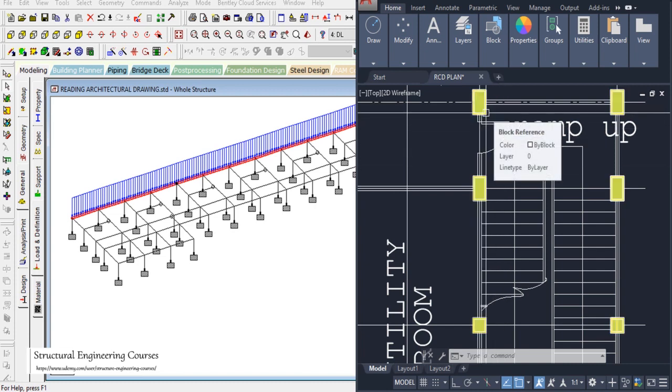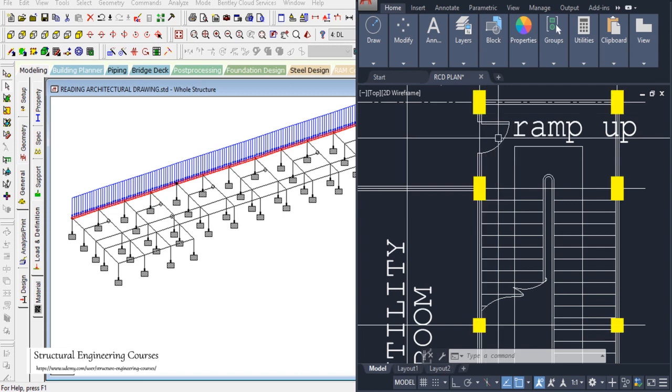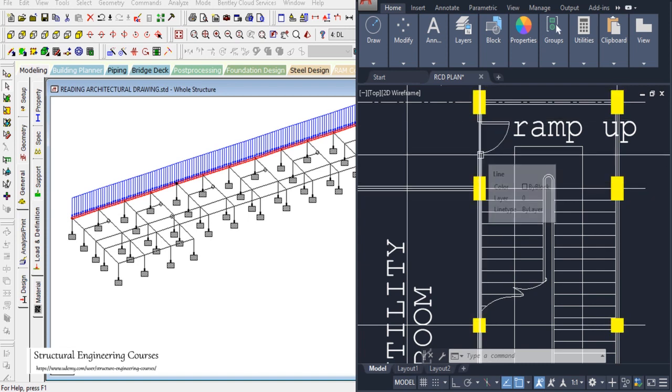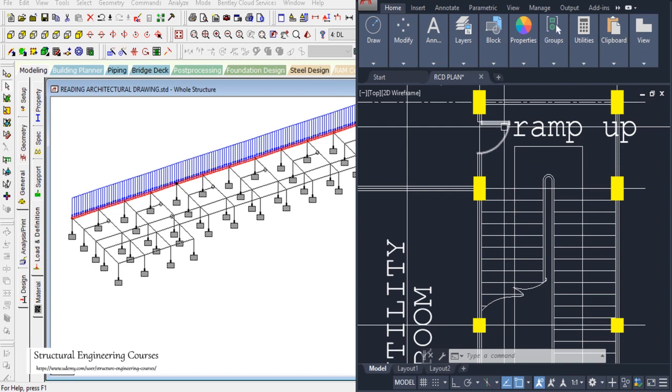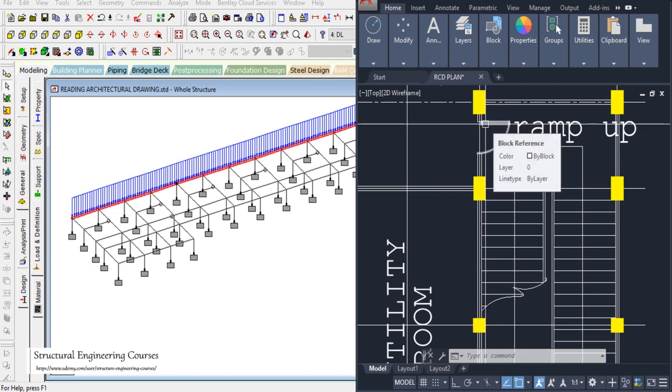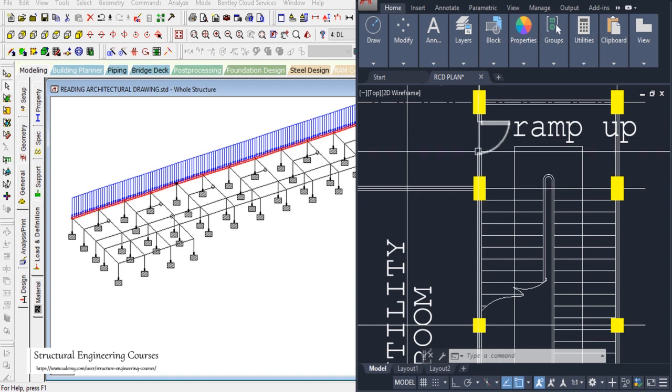But I have seen some engineers who are very particular about all these things, so they apply brick wall loading from this point to this point and from this point to this point, but they don't apply the loading of the door here. Although the door is a light material, if you are doing that much calculation, then you do need to do these small calculations also. This is just my recommendation: always go for the conservative side. There is no harm in that.